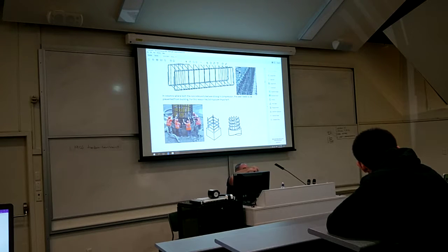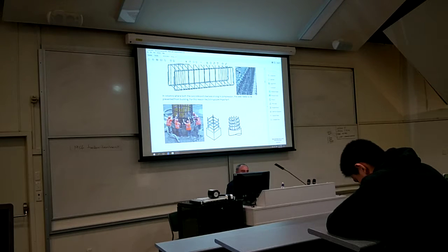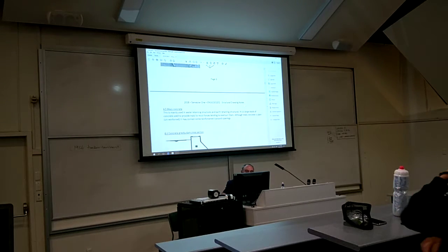Often you'll see little wee hats on top of the reinforcing as you drive around Auckland. That's pretty much so that what happened at Marsden Point doesn't happen ever again in New Zealand, which is somebody fell from a relatively small height, but it doesn't take much more than that to end up with the reinforcing going straight through you. So they're pretty much protecting that from happening. Yes, it would hurt if you had one of those caps, but it wouldn't kill you, unless it was from 8 stories high, I suppose.